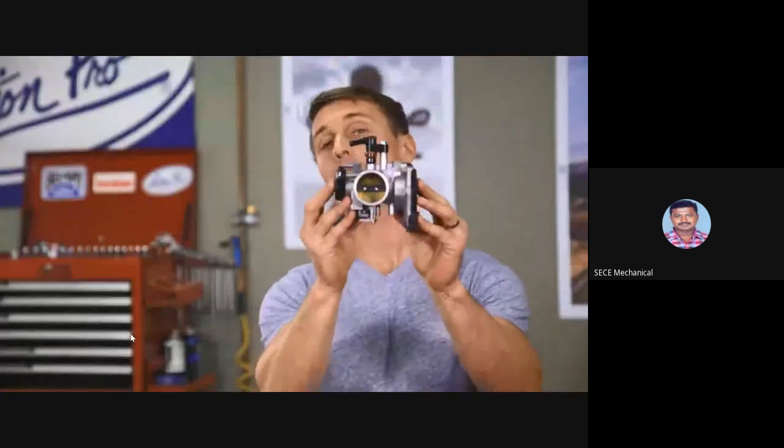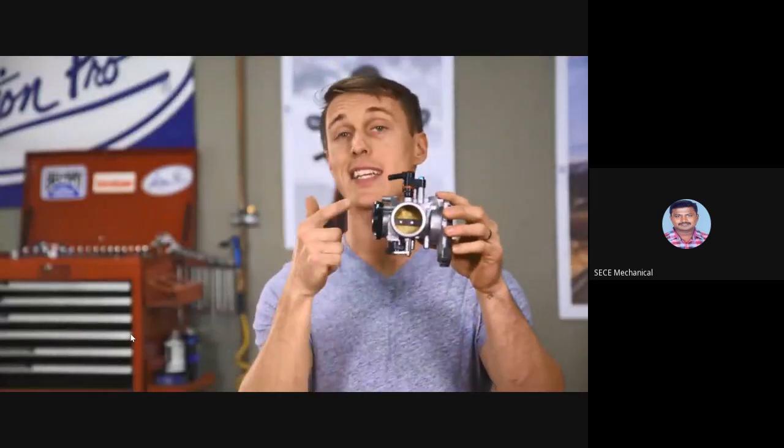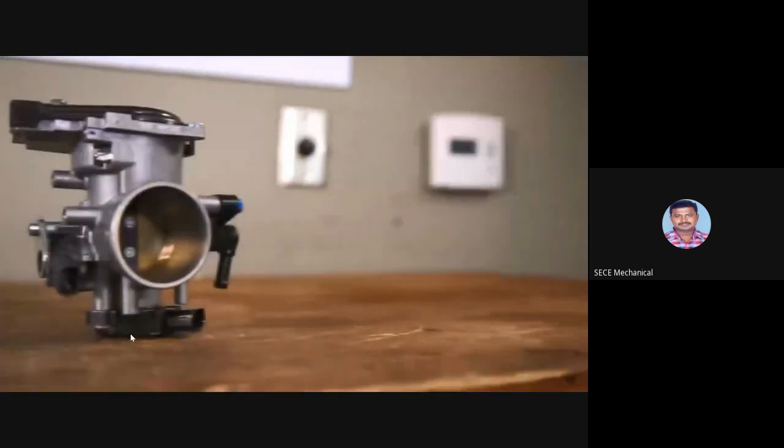This guy may look less complicated than a carburetor, but the fact is there's a lot going on with fuel injection, and there's electricity plus various sensors and circuit boards helping this guy do its job. The main difference is that rather than reacting to pressure changes like a carburetor, EFI makes its own pressure, the fuel pump, so it can inject gas into the engine anytime it wants. With all of its sophisticated components, fuel injection is a far more precise means of delivering fuel into the engine, and that means your bike's going to run better.